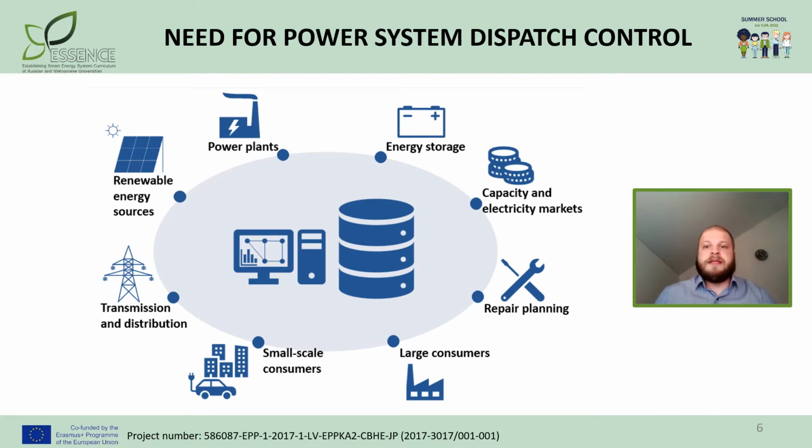When the power system increases in size, the number of substations, transformers, switchgear, and so on, and their operation and interaction become more complicated. So it becomes essential to monitor this information simultaneously for the total system, which is called the energy control center. It's just like a building, the control room, where the power dispatch and control engineering staff provide monitoring and control of the power system state.